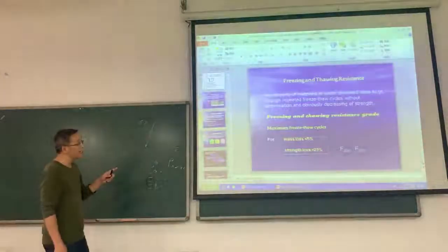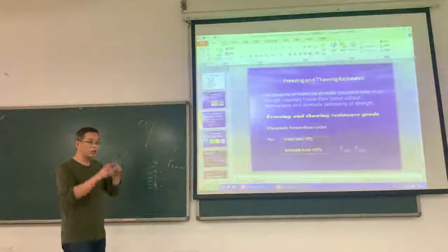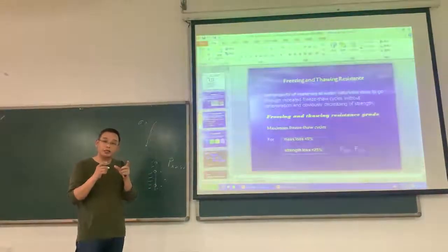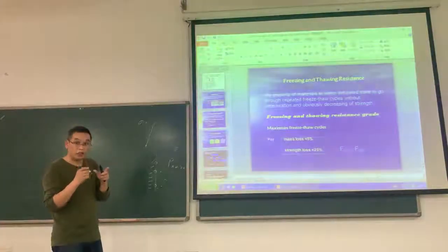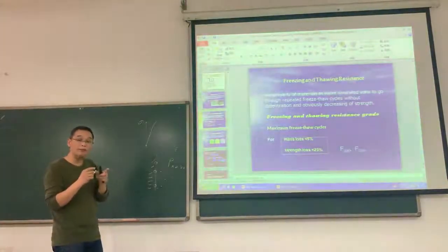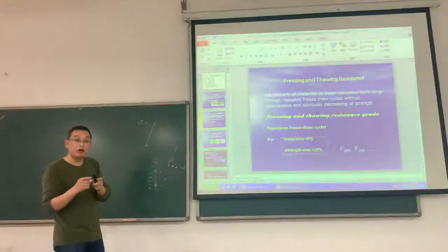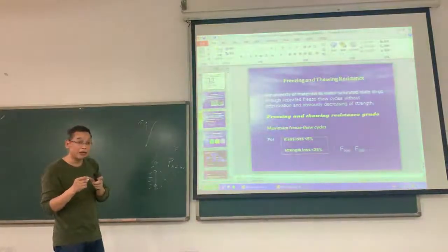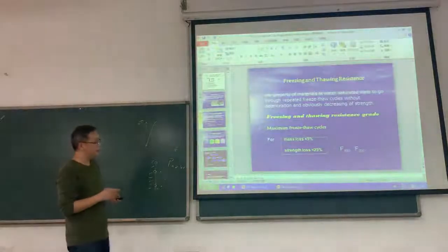Another one is the freezing and thawing resistance. Because when the water is at low temperature, it will change from the liquid state to the solid state, and the volume of the water will expand slightly. So we need freezing and thawing resistance.